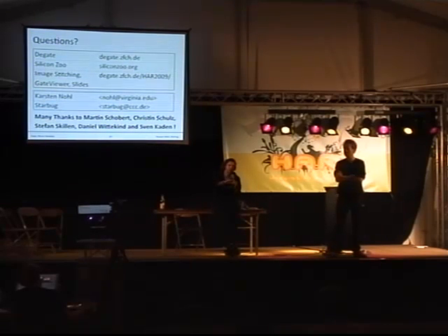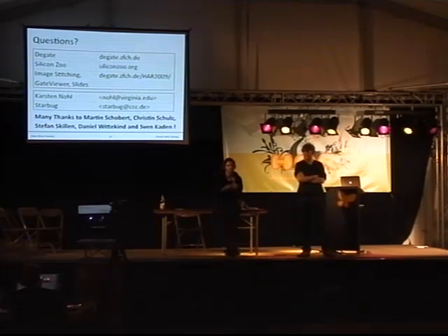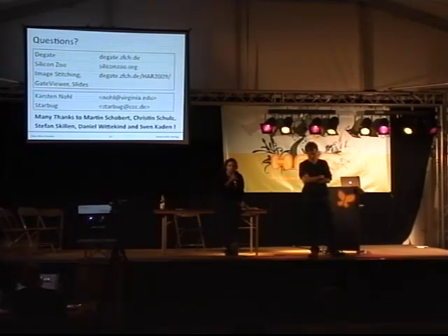If you're trying to flatten the chip so it's not tilted, but it's tilted, you will polish half of the chip, make pictures, and polish the other half and make pictures and stitch it together. So if it's not totally untilted, it's not a problem. It's only a problem if it's an angle of 1 degree or so. But otherwise, it's not a problem to reverse engineer up to 8-10 layers.